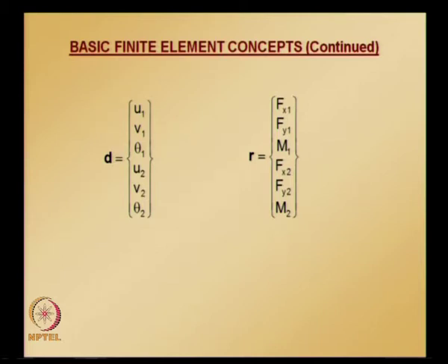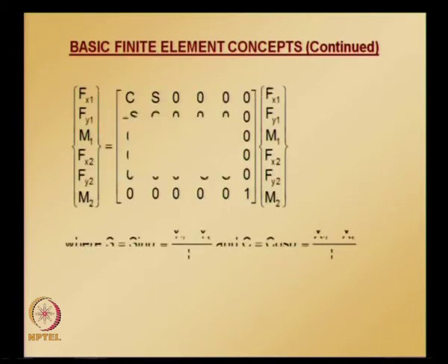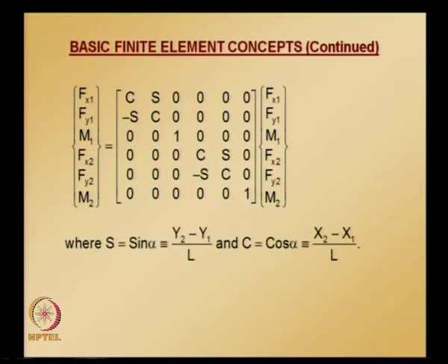A coordinate transformation between local xy coordinate system and global xy coordinate system gives equations that can be assembled directly for any plane frame problem. And that transformation matrix, that is how the local force vector is related to the global force vector, is given by this transformation.